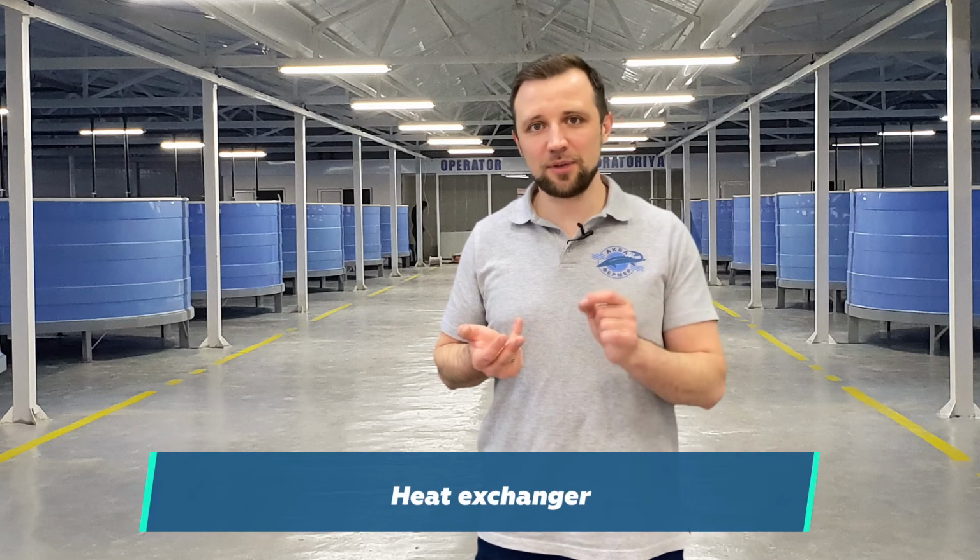Water purified with ultraviolet is very different from the one treated with ozone, and you can compare it. So in general, I advocate for using ozone, and if you select the ozonation designed for RAS, it will not cost more than an ultraviolet disinfection unit. Just about the same, well, at most there will be a 10–20% difference in my region. As for the additional units, such as a heat exchanger, I still recommend to have automatic water heating, not only for the makeup water, but also in RAS itself.